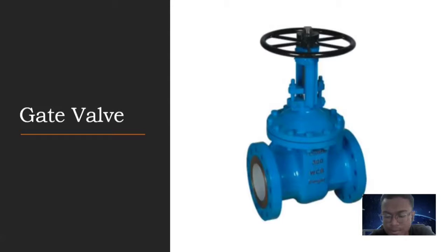The gate valve. The valve controls the flow of the oil in a pipe by moving a flat plate called a gate or a disc. The gate is moved perpendicular to the length of the pipe with the help of a hand wheel. The mechanism is achieved by connecting the gate with the hand wheel through a threaded spindle that rotates in a valve body. The advantage of a gate valve is that it offers little or no resistance to the flow when it is fully open. It is usually made of gunmetal.